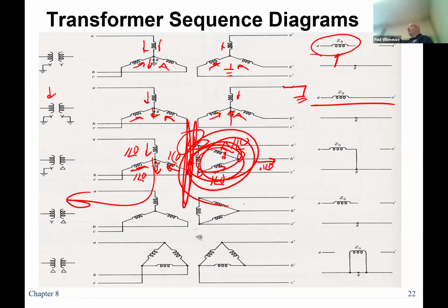This is the best from a protection perspective because I can set my devices very sensitively to monitor ground fault current on one side of the transformer, because that ground current doesn't continue on. So I can set it very sensitively because I've isolated my ground zones. And that's why for transmission systems, that's all we use. Because if you have 1 amp of per unit ground fault current flowing, whatever per unit equivalent current, it might be 100 to 200 amps of ground fault current flowing, you trip. I don't need to coordinate with downstream elements because that ground current only exists between the two delta Y transformers.